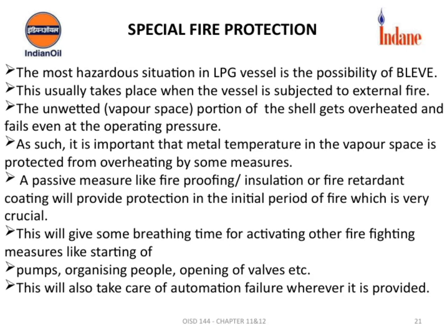Now, let's look at slide 21 from our presentation on OISD 144, specifically chapters 11 and 12. Here, we're focusing on the most hazardous scenario that can occur with LPG vessels, which is a BLEVE, a boiling liquid expanding vapor explosion. This situation typically happens when the vessel is exposed to an external fire. When a fire heats the vessel, the unwetted, or vapor space, portion of the shell gets overheated. Even if the vessel is operating at a certain pressure, this overheated metal can fail, leading to catastrophic consequences.